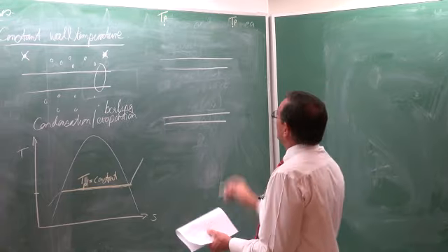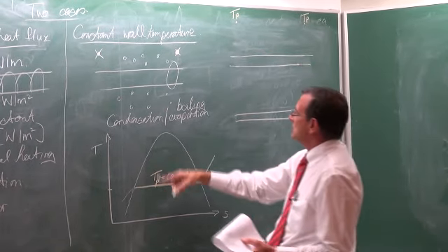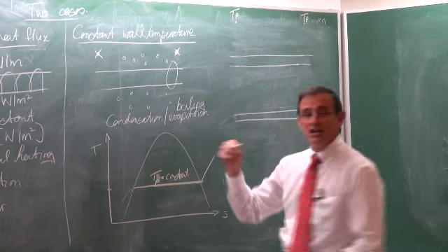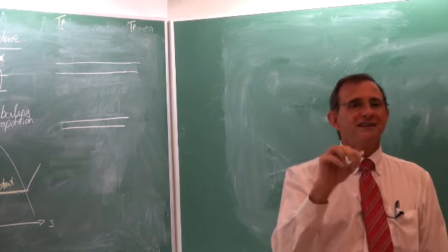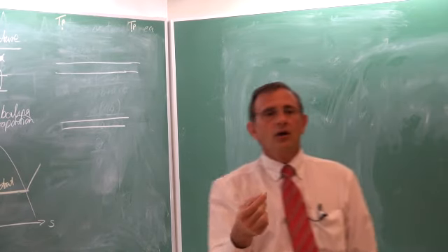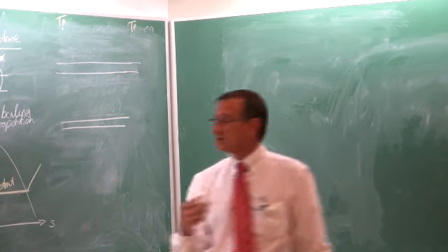Okay. Then, what also happens is that in condensation and evaporation and boiling, the heat transfer coefficients are very, very high. Usually in the order of tens of thousands, while in single-phase fluid, it is typically in the order of hundreds to thousands.